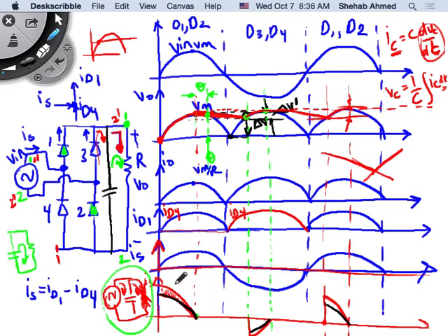Okay. But now, is my load current continuous or not? Let's draw load current. We didn't draw load current after putting the capacitor, right? We drew the output current here, which is the load current, before the capacitor. What does the load current after putting the capacitor look like? Exactly like the voltage, because it's a resistive load. So it will look like this, correct? So we'll have the ripple as well. So until here we explained it.